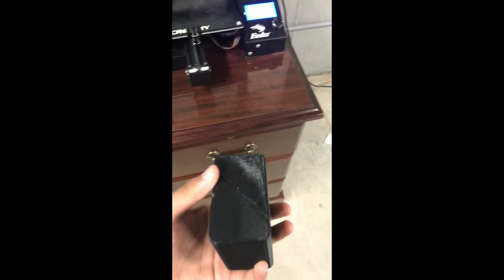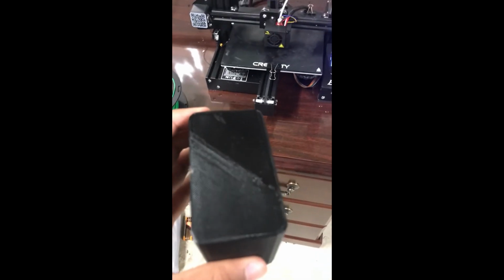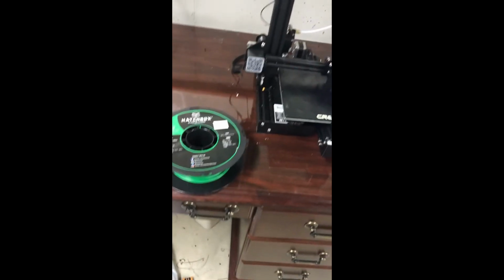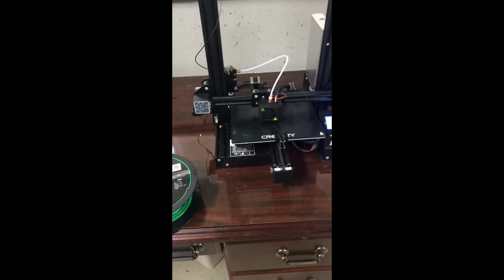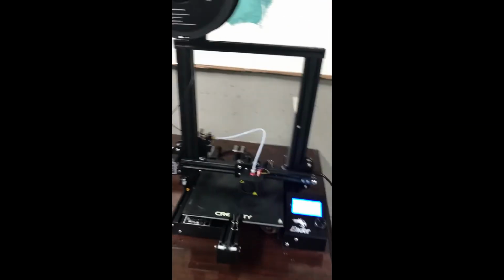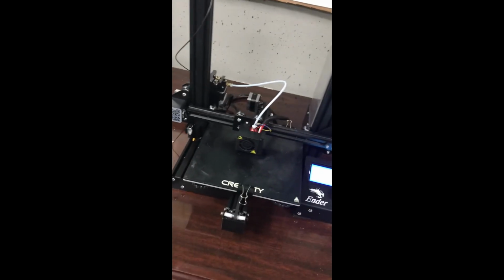So this is what happened in one of my older prints. As you can see here, it started to contract on this side and it pulled the print off the bed. This side's flat, but you can see how it started to warp over here and curl towards this one edge. There are different ways you can help this. When you're modeling the STL file, go ahead and add a little bevel to the edges, so it's not just a sharp edge, as that tends to help. But other than that, using an FDM 3D printer is pretty easy. Once you get the settings right, you can learn to play with it however you want, get the results you want out of it, and it'll work just fine. I love my 3D printer, and it works pretty well for me.